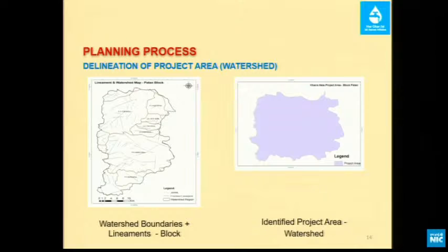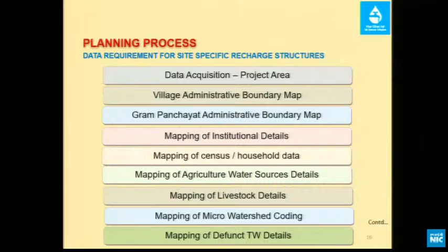Based on my topo sheet areas, I have delineated the watershed within that block, and I have considered only three things here. I don't know whether my area is rechargeable or not. Number one, soil. Number two, geomorphology. Number three, structural geology. Once my conditions are okay and my area is rechargeable, I can proceed further. So this is a planning process.